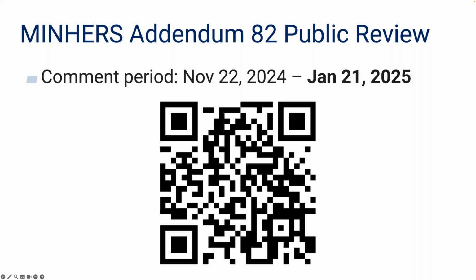Another piece of it is the fan airflow and blower watt draw parts of grading. Now that you have multiple modes and multiple speeds potentially operating, you need to know which speed and mode you're operating at when you do that draw, so that you can then extrapolate out. There's certainly going to be complications, but I don't see the grading process as something that is not going to be reliable moving forward. I think we're going to be able to figure out ways to clarify some things as they arise.